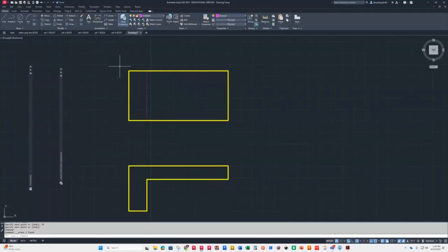You could also do it the cool way and go up here to your diameter circle. You could hover over this middle line right here and just move your line over and type in 35. And Mr. Doty does it the mystery way, and 18. It doesn't matter how you get there, right? So you could offset over 35, you could draw a line from the middle of the line over 35, or you can use your O-tracking and do it as well.